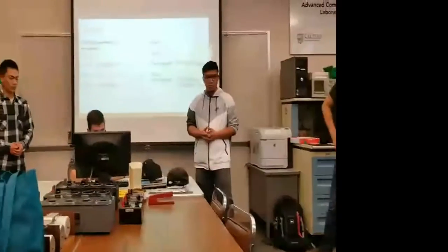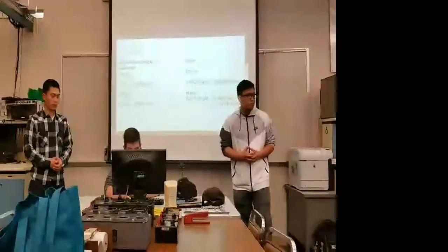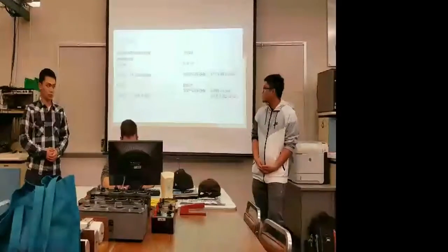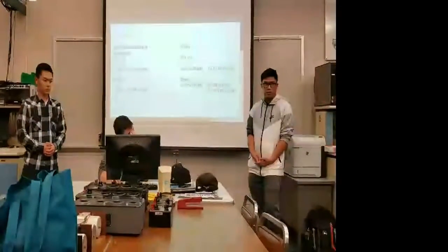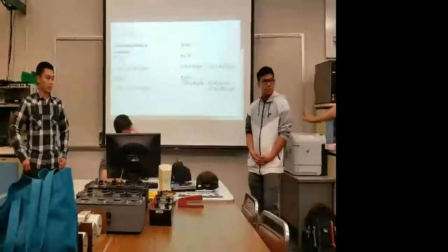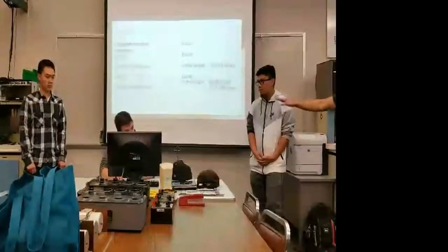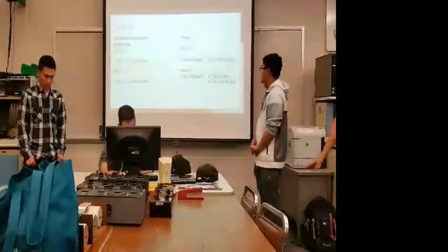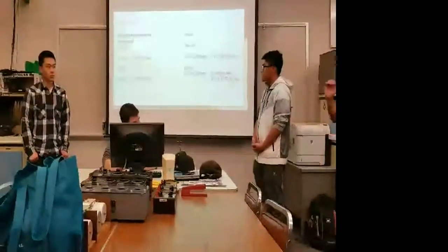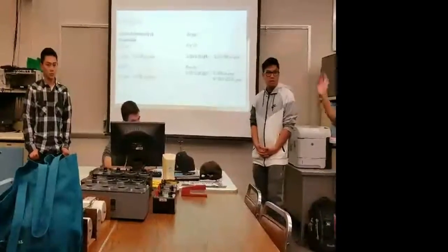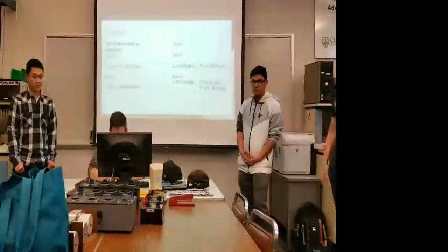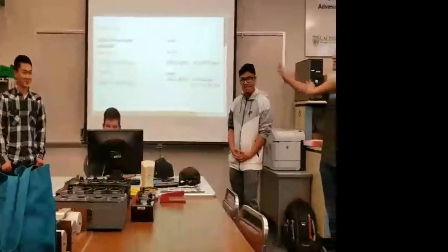So let's start with the amplifiers. This gave us the most trouble by far, and really set back the project. We started with the 3+, and you all know from the data sheets that at around 2 gigahertz it's like 18 dB of gain, 15 is fine. I don't know anyone that got up above like 17. I don't remember, but ours was around 12 and 13.